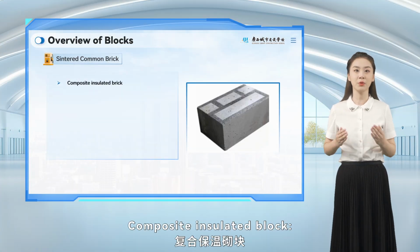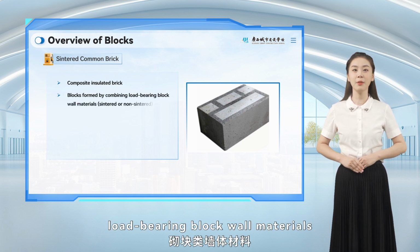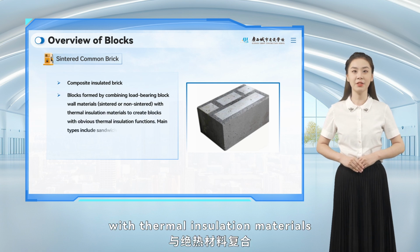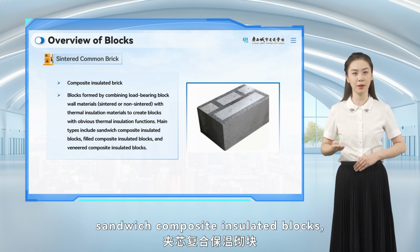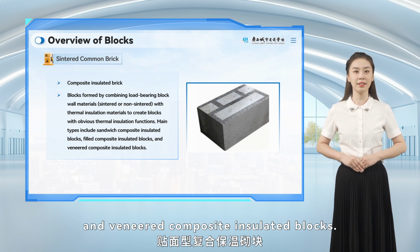Composite insulated block. Blocks formed by combining load-bearing block wall materials, sintered or non-sintered, with thermal insulation materials to create blocks with obvious thermal insulation functions. Main types include sandwich composite insulated blocks, filled composite insulated blocks, and veneered composite insulated blocks.